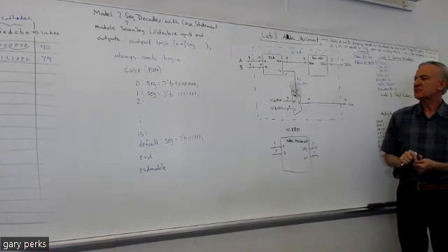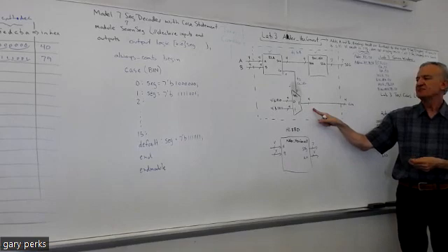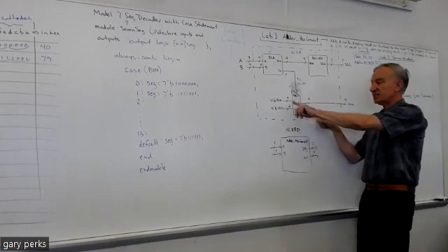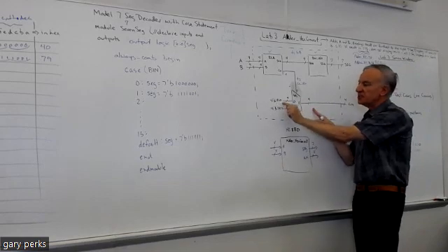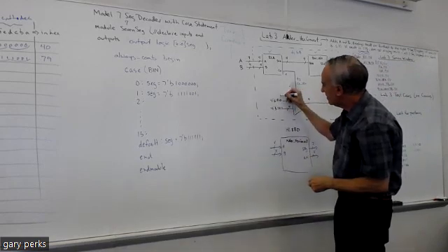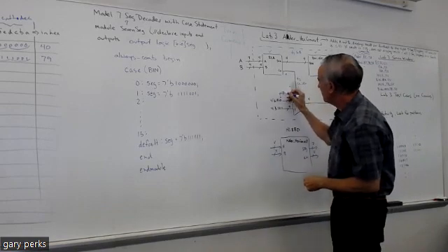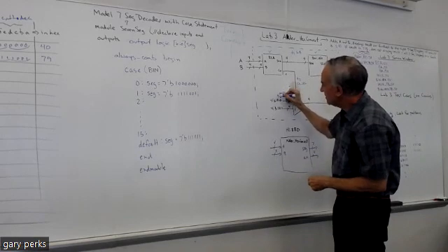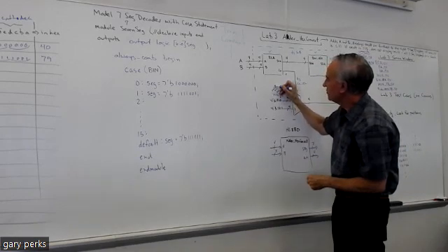So with a 0 on the select of the mux, which of these two is the output going to be? It's going to be what's connected to input 0, which is 1, 1, 1, 0. So you see this 0 here, that's going to become AN, the 0th bit, and then the rest of these, AN, the first bit, AN, the second bit, AN, the third bit.